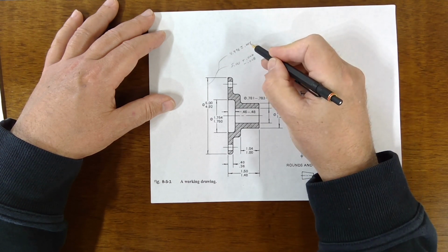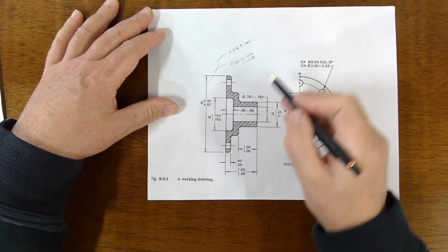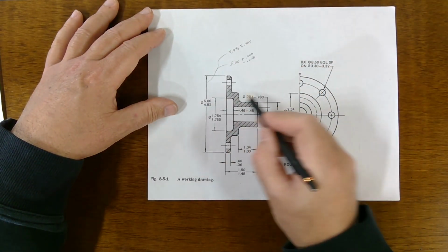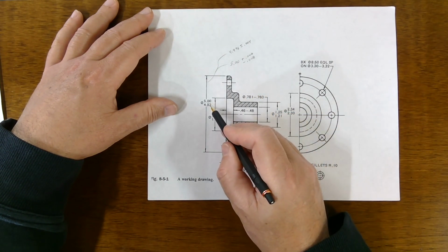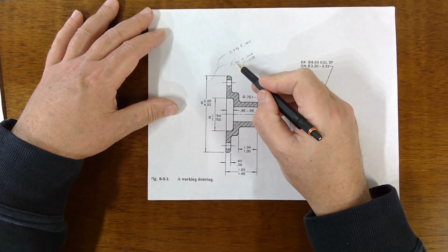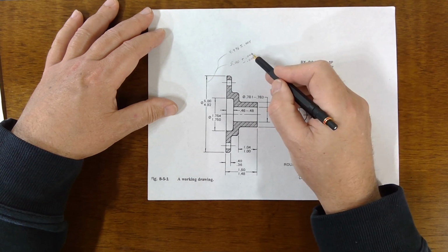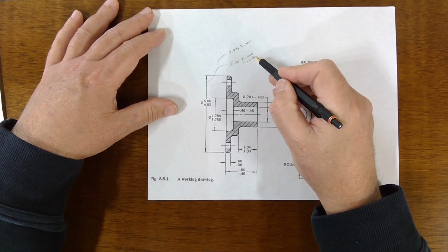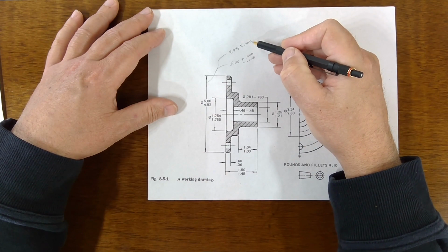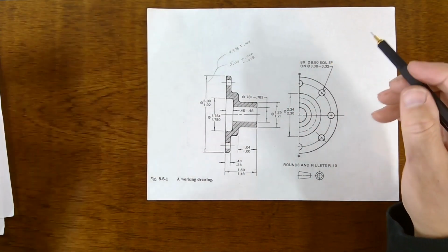So then if you added 0.04 to this, you'd get 5 exactly. And if you subtracted 0.04 from this, you'd get 4.92. So those are three ways to specify a tolerance: either min and max over each other, put the dash in between, or you can do this base dimension, you could call it, and then a plus value and a minus value, or you could make the plus and minus values the same. Here they're not the same, but here they are the same. Different ways to specify the same thing. All right.